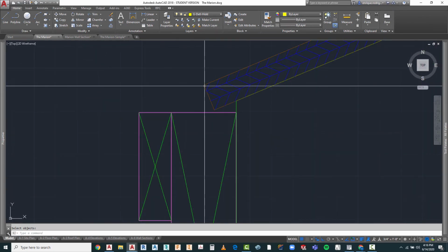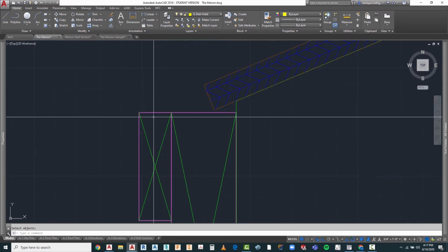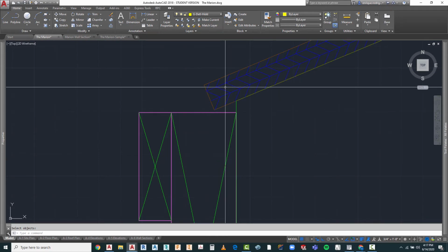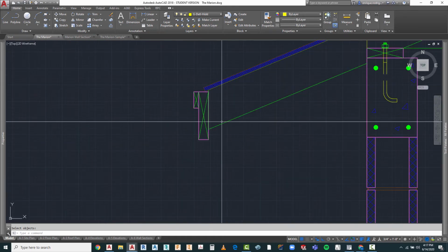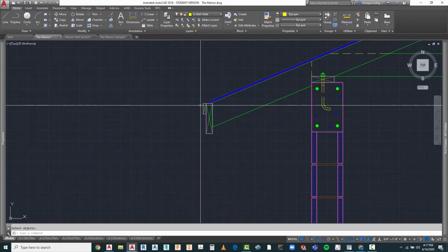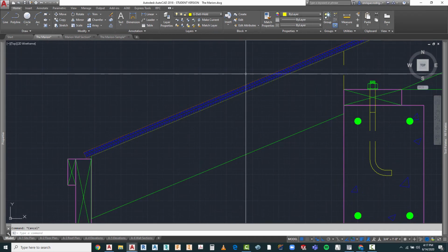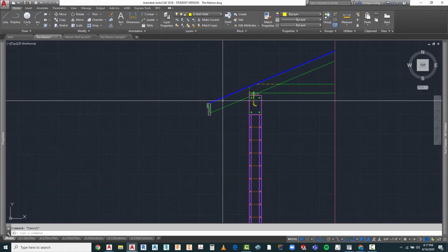One thing they're not going to do, and I've seen people draw this, is draw the plywood so that it just rests flat onto here. No one's going to rip a piece of plywood at an angle like that at the edge. I think that's something you don't want to do. So let's bring our metal flashing in here before we start adding any of the roofing materials that are going to be indicated up on the top of the roof.